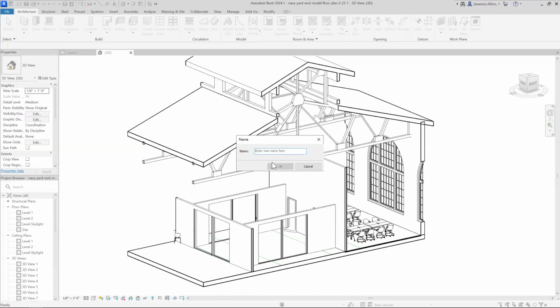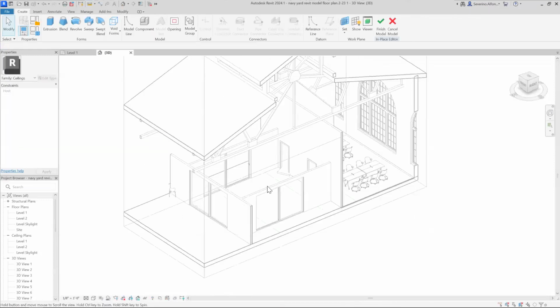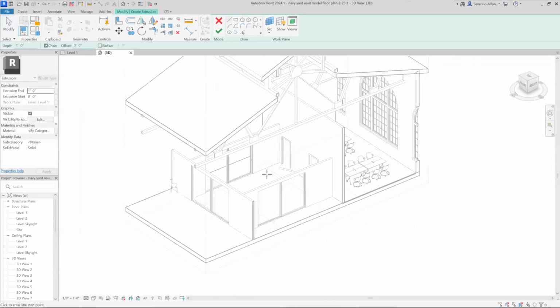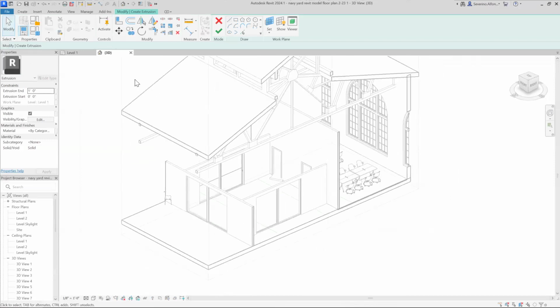I mean, you could do one by one, or you could do a space one and give here the name, like lobby, whatever, or you can just do most of the ceilings in one-to-one space. I'm just going to do it as space one condition, and you figure out how you give the names. Remember, we enter these tools, so I'm going to use the extrusion. But one thing that is important is that to create an extrusion, if we click here and show, we're going to draw lines or curves on that blue grid, and then the extrusion is going to be perpendicular to that surface. So we want to change that.